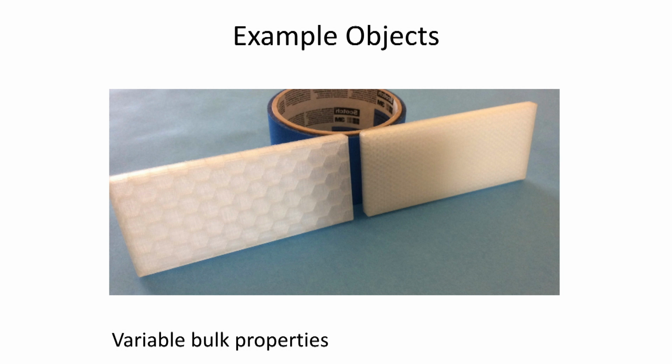So we want that low modulus so that the bone in the patient that's interacting with our titanium 3D printed part doesn't stop growing, because that bone continues to experience stress. The titanium part, which is now more flexible because of its low infill and therefore its low modulus, remains flexible, the bone continues to grow, and the patient doesn't suffer from osteoporosis, for example.